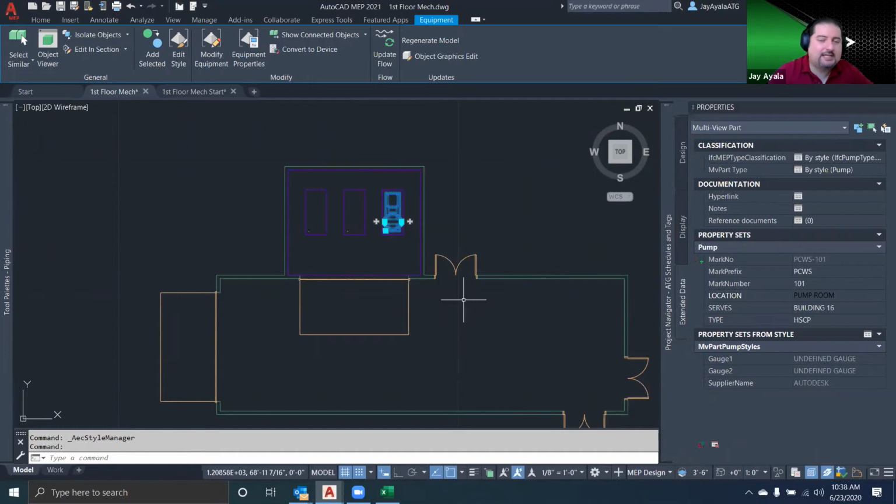I did want to get into those details because by doing so, we have the ability to create additional pumps by using the copy command, and it would automatically increment the digit for you by leveraging that format type. So that's how we create property sets. A lot of them are going to be manual, some of them are going to be automatic, and then there will also be ways where you want to use any kind of algebraic formula to have a formula type of property. In my case, I just concatenated a string based off of a prefix, a dash, and a number.